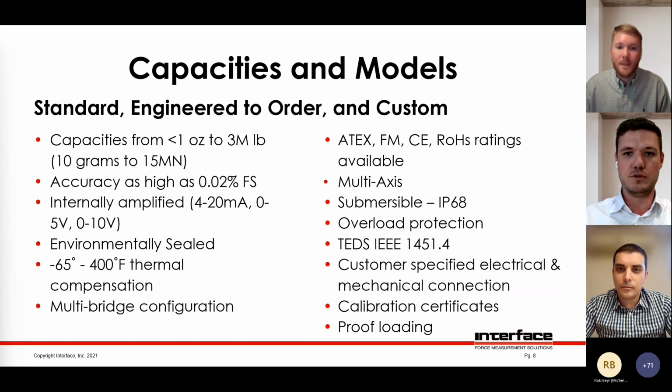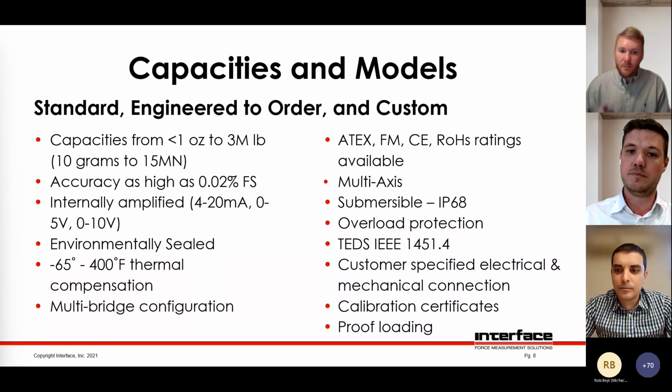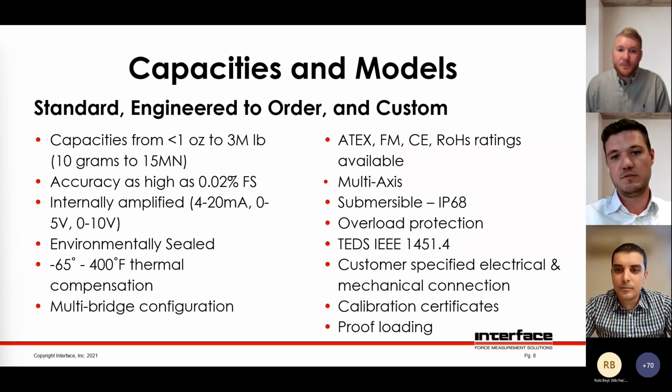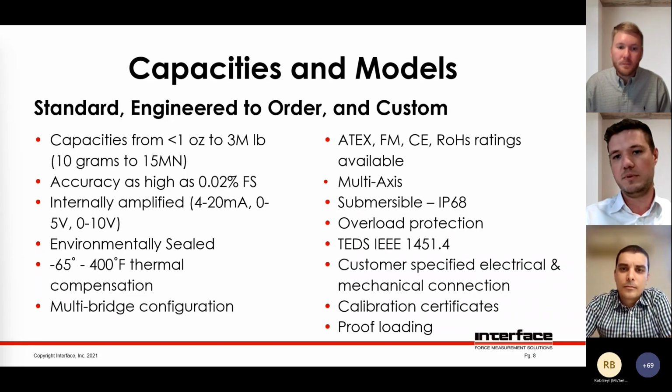We can do explosion proof, as we mentioned before. CE compliant, RoHS compliant. Submersible, we do IP68 load cells for use in wave tanks or subsea applications. There's mechanical overload protection for some of the load cells, especially the smaller capacity, where we'll talk a bit more about overload later, I think, but you can physically stop the load cell from being overloaded.